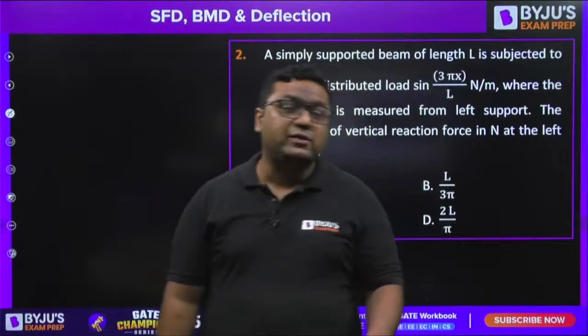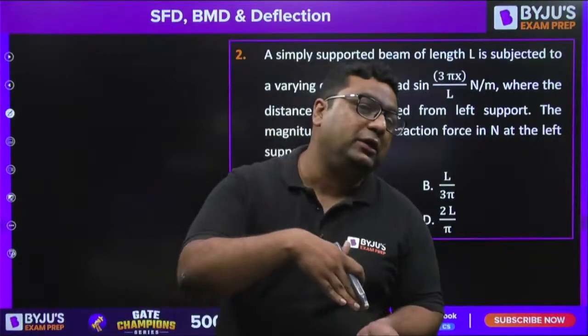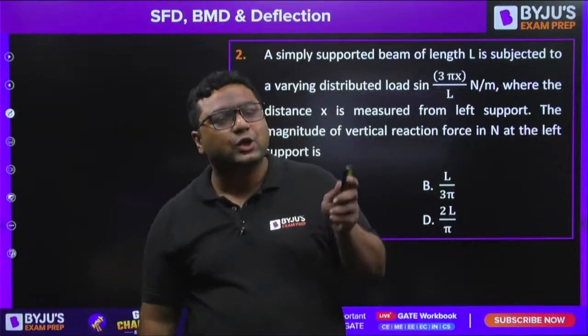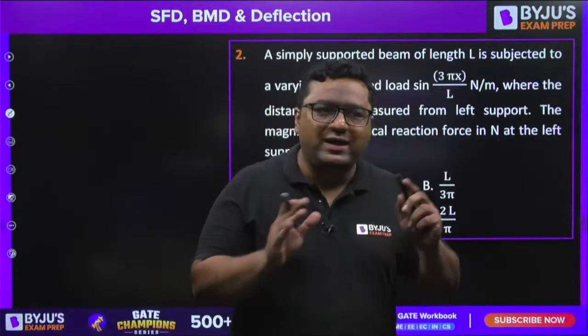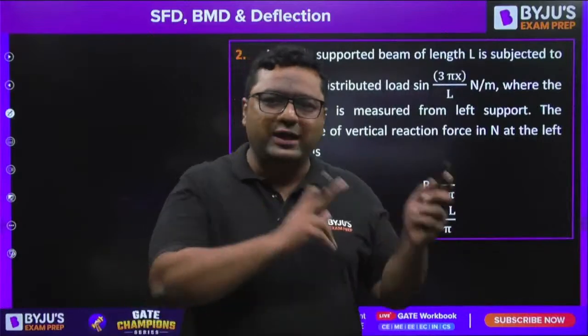Yes, Shubhankar, I have considered the right hand side, because if you take the left hand side, you need to find out the support reactions. So whenever you have one end free and the other end fixed, it is better to take the right hand side.